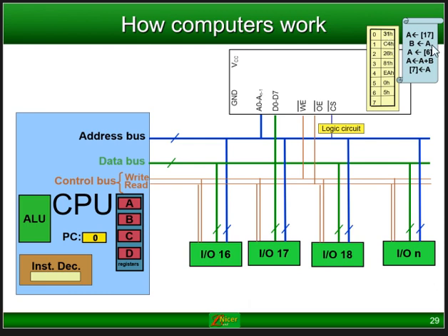If you look at this scroll here on the right hand side, it actually means that instruction 31 in this specific case, it's just an example, means go to address 17, which means it's this one here, and collect the content and place it in register A. This is what 31 means.